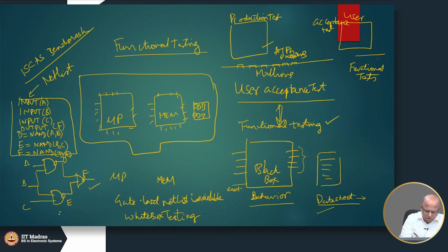So, this particular circuit that is shown here, it may have some functionality to perform, okay. It may have some description, but the ATPG does not care about the description. It only cares about how I can activate a stuck at fault, how I can propagate that fault to the primary output, that is all it cares. Okay. So, that is an important thing that you must understand, right. So, the ATPG test patterns, they do not understand the circuit.